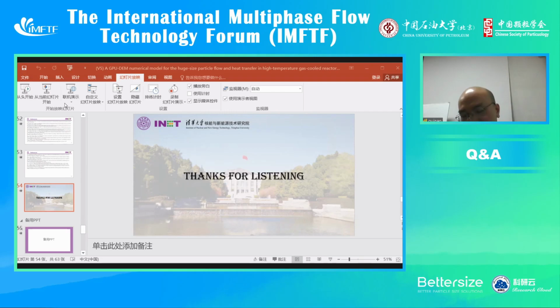However, we also developed another kind of method, a subcell particle method. I just didn't show this kind of model in this presentation. In the subcell particle radiation model, it can calculate the finite conductivity of the particle material. So we can use the finite conductivity of the particle in the radiation heat flux prediction.